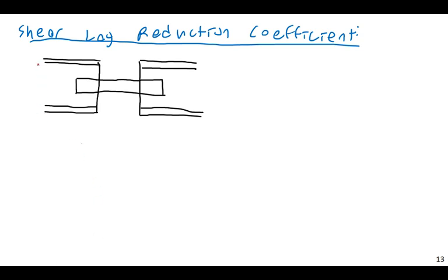And this would be tensile stress here. So let's say over here we have the entire cross section engaged, like this, in tensile stress, and same thing over here, like this. But it all has to get here. There is no material here or here to carry that tensile stress. So instead, the stress has to flow. It has to concentrate and flow through the material to get concentrated enough to pass through the smaller member. The stress has to concentrate.